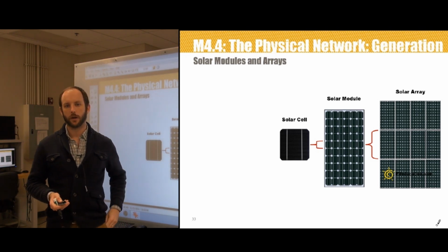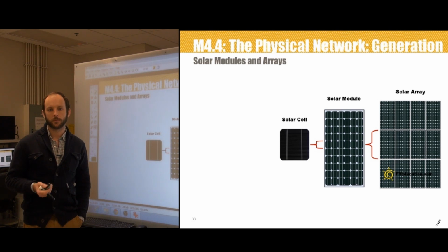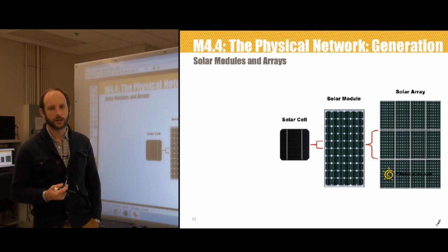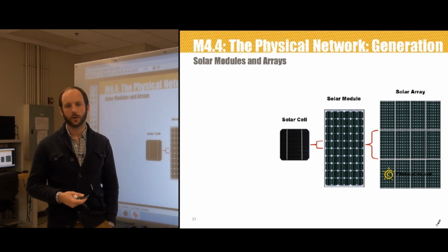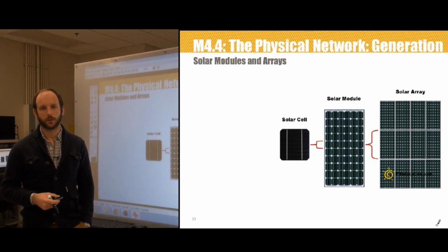Like cells, modules wired in series are going to increase total output voltage. However, when more current's required, cells are wired in parallel. So arrays will have different series parallel configurations to develop different power to the load.